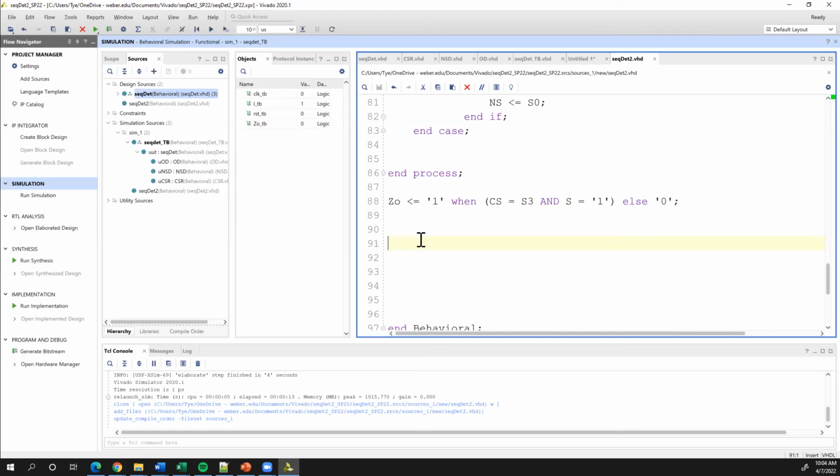Is this the same way you would set up for the lab we're going to have today? Yes, this is exactly what you'll do for the lab today. However, I'm going to show you an even easier version. So what this has done is we've built 3 different blocks just inside of one file, which is simpler by far than trying to figure out the next state table and the K-maps and on and on. I just use conditions, right? If this is my situation, then go here, otherwise go here. It simplifies it. But it turns out we can simplify it even further and I'm going to create a new source.